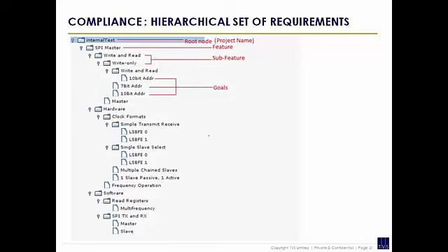This is SPI actually rather than R². See that there's similar things. What we would do in our hardware, and this is for an ASIC, I think, where we said, right, for this SPI master, we've broken it down to reads and writes on the bus with a 10-bit address, 7-bit address, 10-bit address. There are verification goals. These are the sub-features.